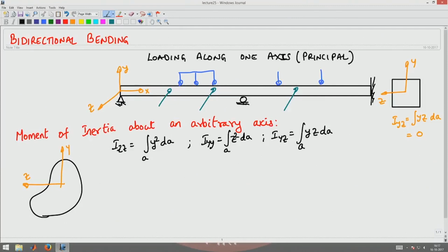Now, as usual, like what we did for the stress component and strain component, this moment of inertia is about an axis oriented in a particular direction, but two of us need not agree on this orientation of the axis. So, let us ask the question, what happens if someone comes and rotates this axis in the anticlockwise sense to y star and z star, where this angle is theta.